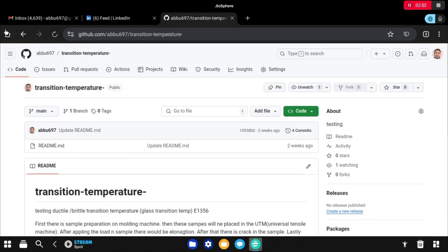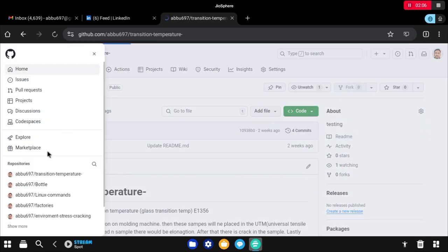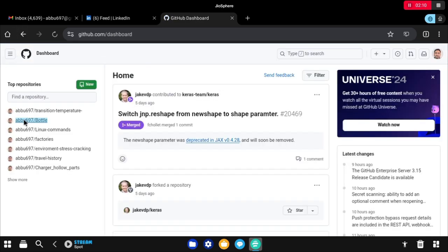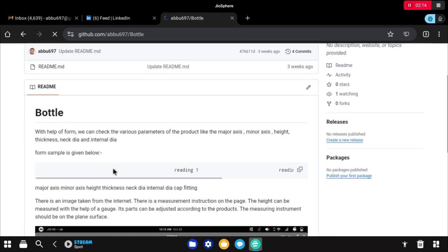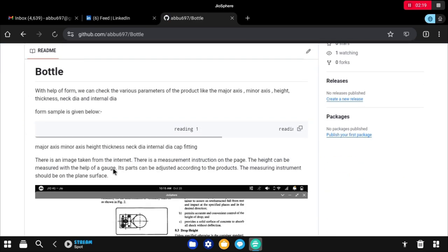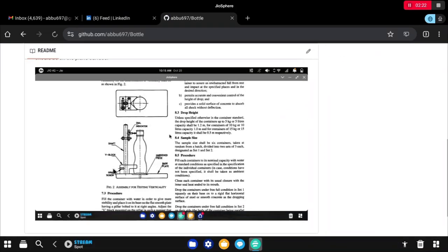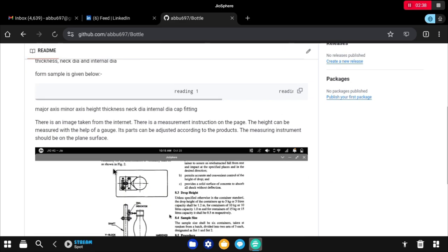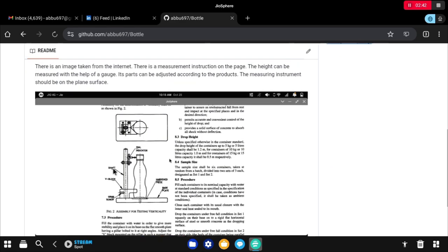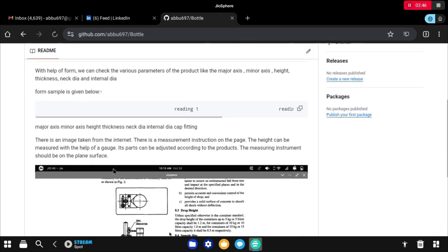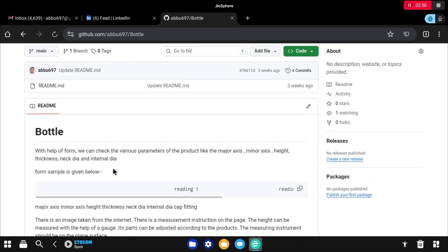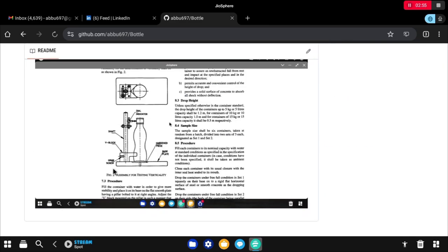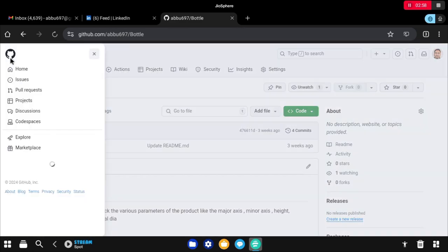Now the second topic is the different bottles which we are making on the blow molding machines. First there is the medicine, then there is blowing in the mold. So there are different types of bottles with different capacities. Then the testing is there. We can measure their dimensions, length, width, height, and also do the leakage test, and also check the cap on the bottles.